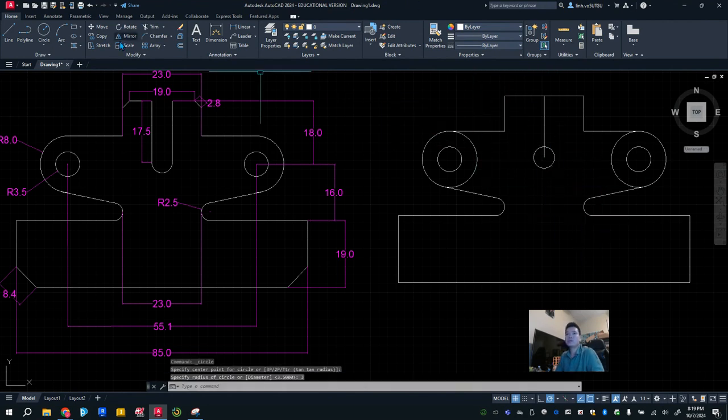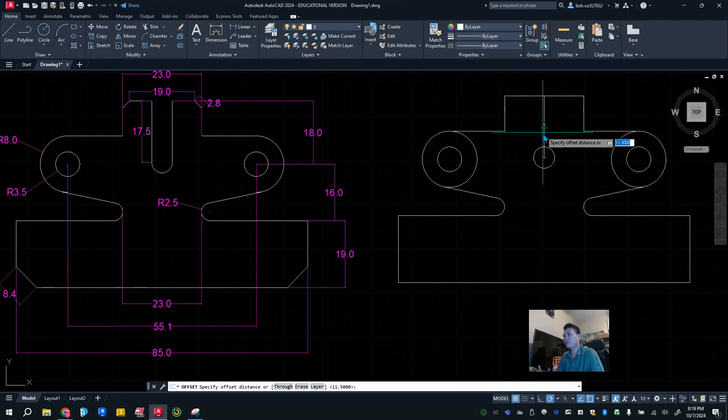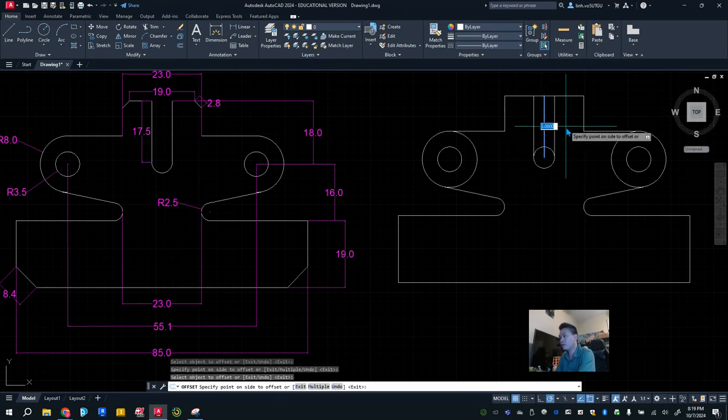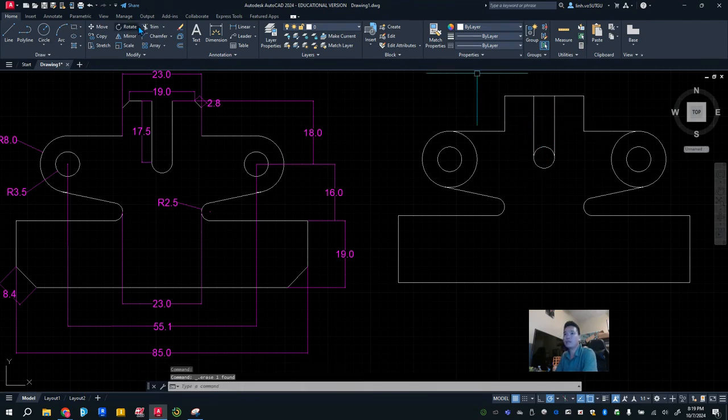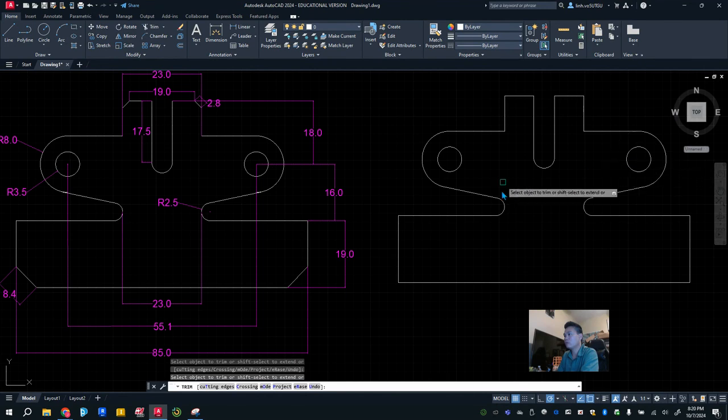Okay, so now what we're going to do is offset our things, 3 radius to the left, 3 radius to the right. Hit escape, get rid of this, and then trim this section. Trim, trim, trim, trim. Okay, so now I have that trimmed. Everything look okay? So let's trim this one as well. All right, you guys can see the problem.